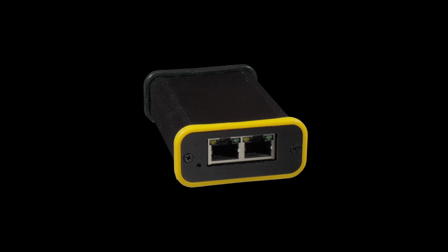The LEDs on the top of each port indicate the link status, although current firmware support for this is rather limited, and the only two states are blinking green, indicating it's looking for an E1 signal, trying to align, and solid green means that a valid E1 lock has been acquired. In the future, more link status reporting like no signal or CRC error, remote alarm and stuff like that could be reported using the off state and the other amber color LED. Again, the wiki doc will be updated once this is implemented.